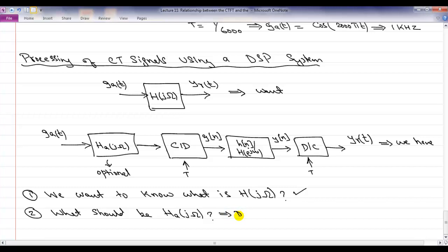This depends upon the choice of capital T and the nature of your input signal. And you can determine that, again, using the information that you have available. You could say, well, I have a signal which has this bandwidth, so I must use big enough capital T, or my signal is not guaranteed to be band limited, so I'll have to pass it through first a low pass filter. That's not a big issue either.